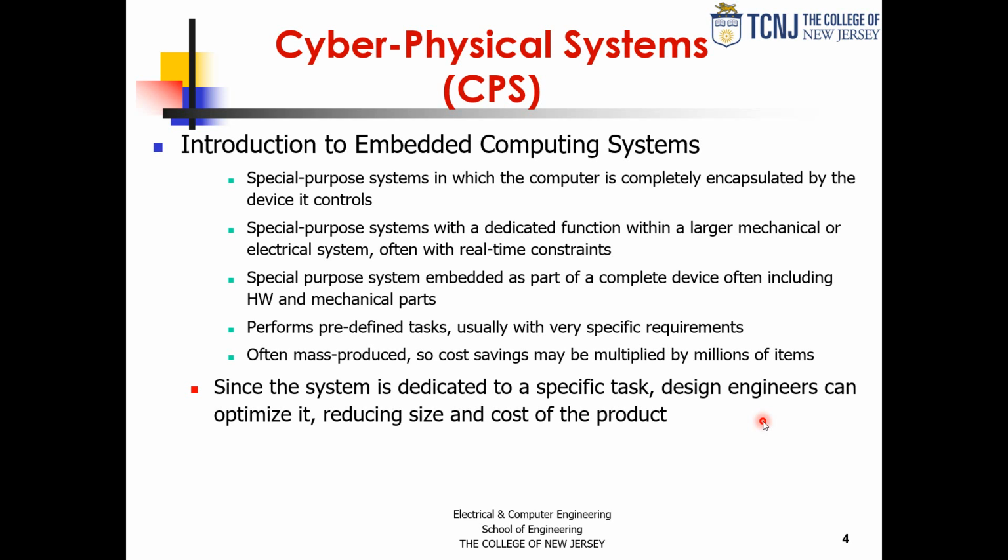Up to a point. We're not talking about hardwired type chips, although we're going to make a further distinction within embedded systems. We're going to talk about the processor-driven embedded system, which allows you to do a great deal up to certain performance, but then at some point, if your embedded system requires higher performance, you have to transcend to programmable logic. So we're talking FPGAs, and those still work together with processors. So it's the addition of that programmable logic fabric that allows you to get that next level of